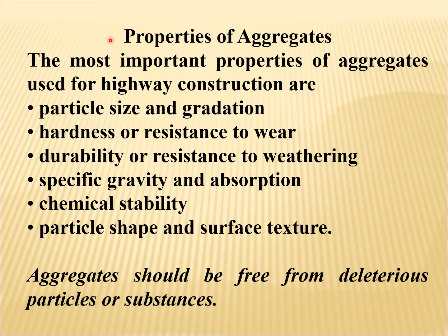Properties of aggregates. The most important properties of aggregates used for highway construction are particle size and gradation, hardness or resistance to wear, durability or resistance to weathering, specific gravity and absorption, chemical stability, particle shape and surface texture. Aggregate should be free from deleterious particles or substances.